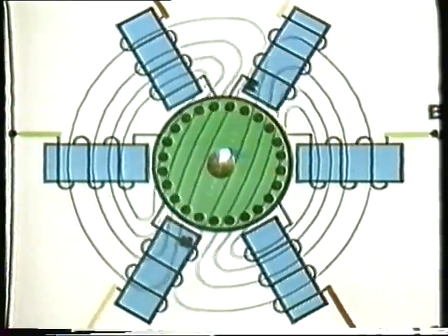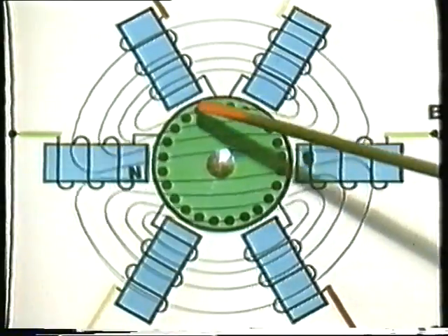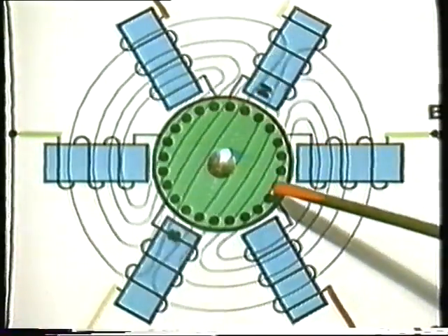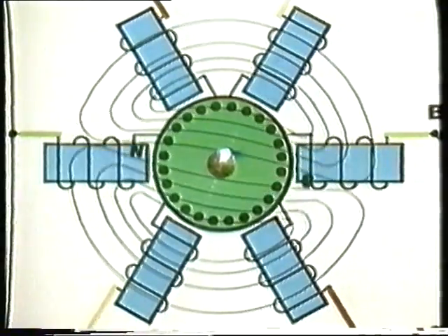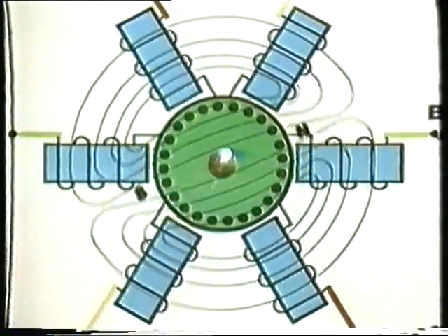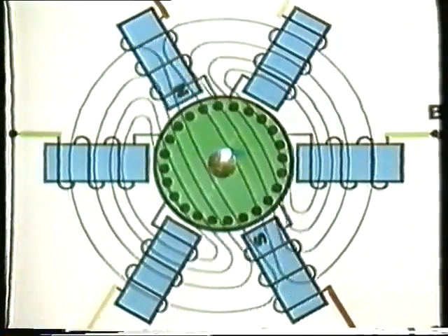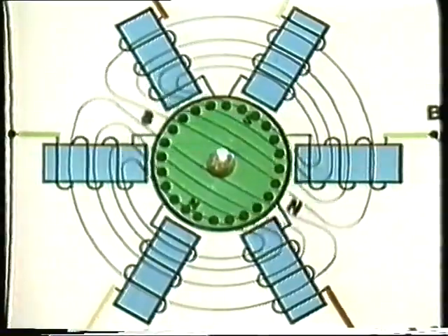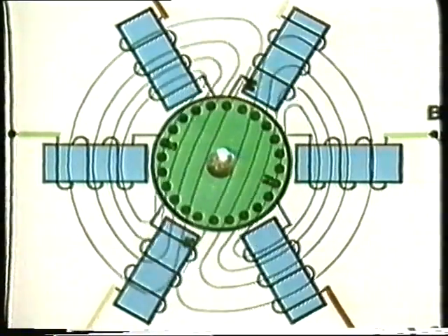The rotating flux lines sweep past the stationary rotor conductor bars rapidly and induce maximum voltage in them. Resistance is low, and high currents flow in the conductors. These rotor currents produce strong rotor poles, which follow around the motor between the stator poles.